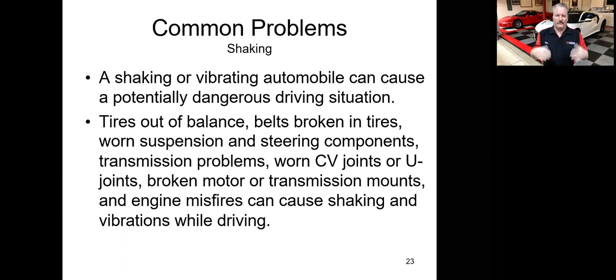One of the most common ones is when you're driving down the freeway at 50, 55, 60 miles an hour, your foot is not on the brake pedal, and the steering wheel is doing this little shake, just a little shake like that. More than likely a tire or wheel is out of balance on the front of the vehicle.